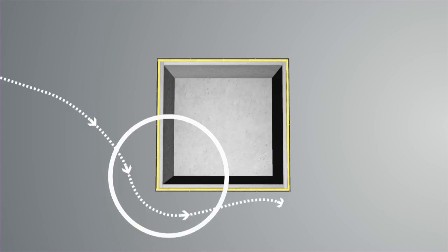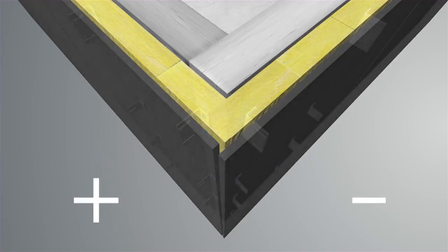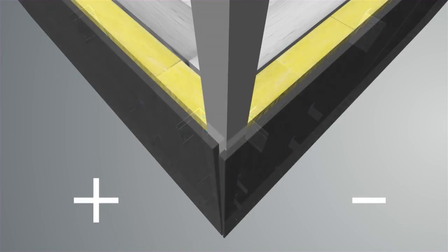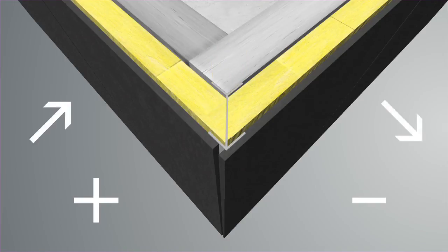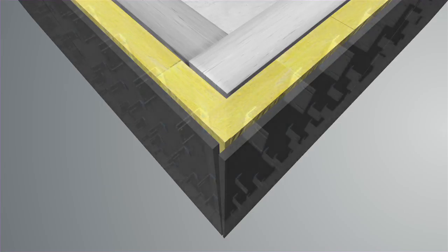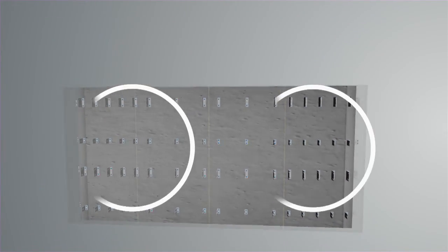External corners are one of the most vulnerable areas to wind. As well as the wind pulling the panel from the outside, the back of the panel can also be subjected to pushing from the cavity. To counteract this, a continuous vertical cavity closer is introduced so that the wind pressures are separated. Another solution is to fix extra supports on both sides of the corners of the facade.